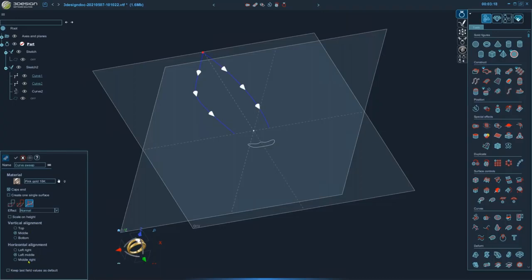Obviously a 1, 2, and 3 rail sweep and a 4 rail sweep are going to have different alignments. So for now, be sure to check your alignment. If you go to sweep and it looks funny, part of your section is way outside of the shape, that's because of the alignment. So don't forget that third tab. Check your effect for the rotation and your alignment. But yeah, those defaults are being updated in the update.